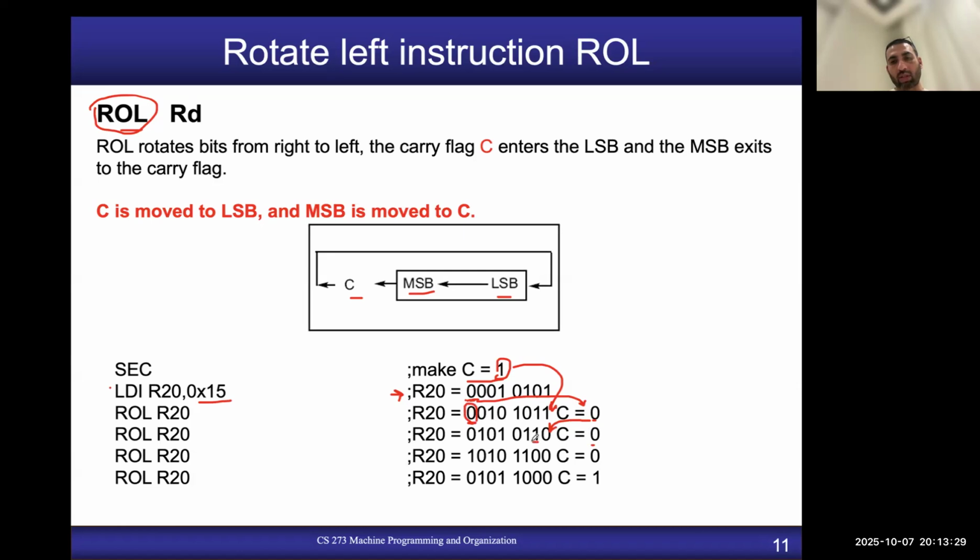So these two ones are moved to the left side, then you have 0 here, this one is moved here, this 0 is moved here, this one is moved here, and 0 is moved once to the left, and then this 0, as we said, which is the most significant bit, goes to the carry here, right? Any questions here? I don't want to go to the next rotate on left instructions, but it is pretty clear how things are working here. If not clear, let me know.